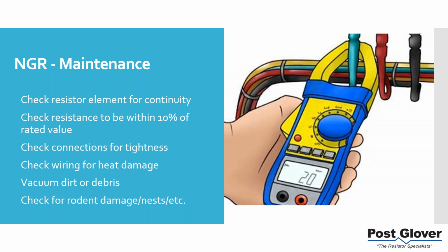Check connections for tightness. Check wiring for heat damage. This is not typical if everything's hooked up correctly, but sometimes you may have a cable overhanging on the installation or something that's not done quite right. You want to make sure that doesn't happen.